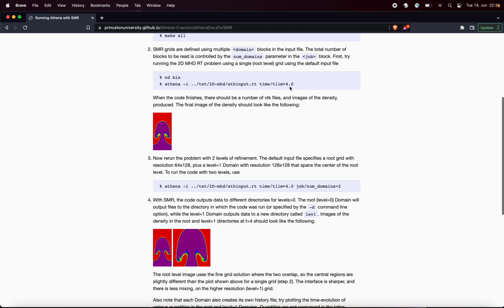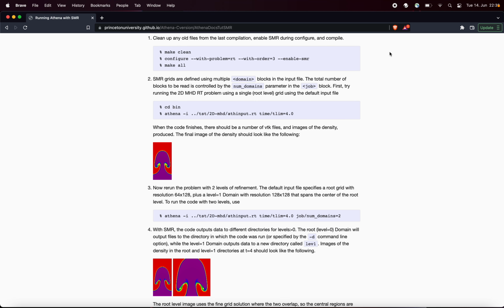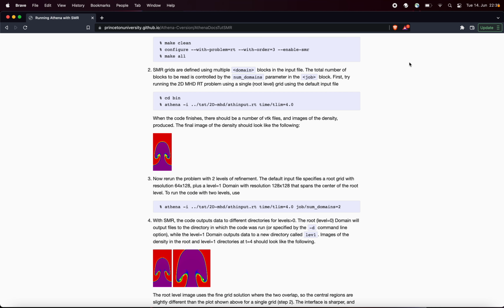So you can have a uniform grid, high resolution region surrounded by a box of lower resolution, which spreads you out before you reach the actual boundary condition. There is a bit of a refinement jump and therefore it almost acts as a boundary condition, but in any case, this is useful but not required for our present purposes.